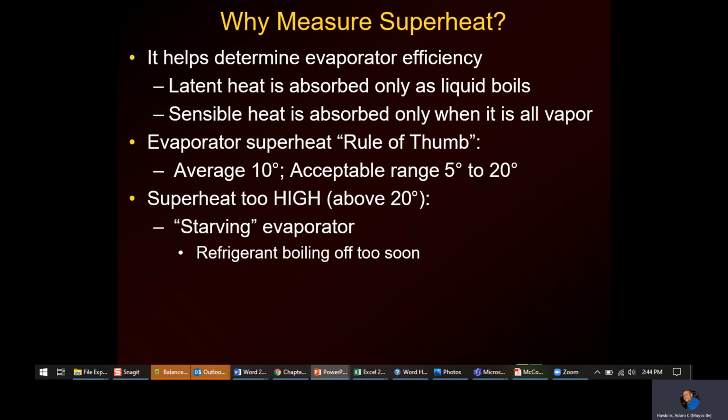It could be caused by too much load in the house. It's really hot. But that's why you would need to understand all those factors. You would need to line all those up to say, does everything else indicate that it's low on charge, or is it something else? So that's where your little troubleshooting charts come in to say, what are the symptoms of X, Y, and Z.